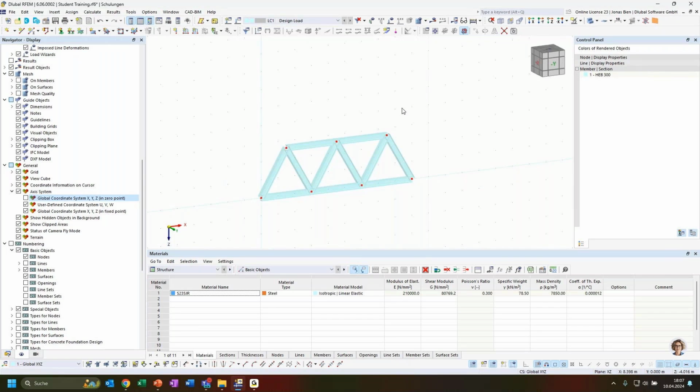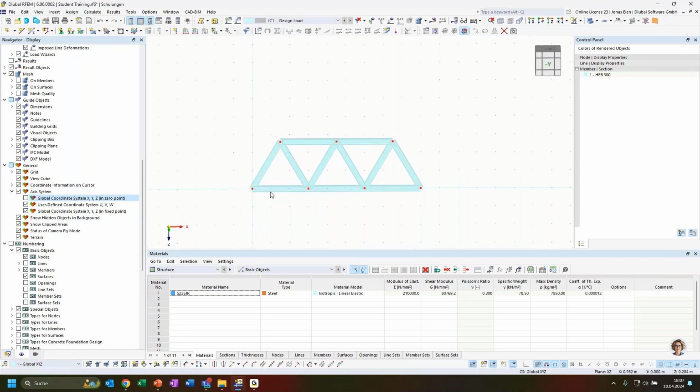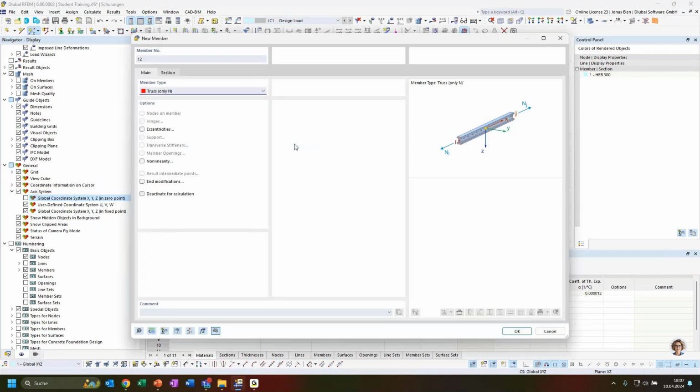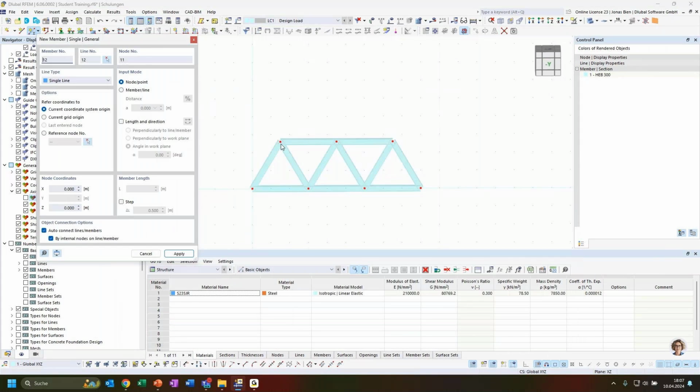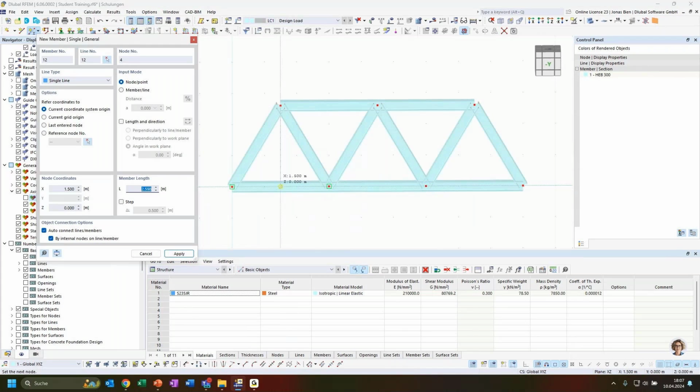So that just leaves me with the missing vertical truss members that, so to say, divide my triangles by half. So I generate additional truss members, and I create them by selecting this upper node of my first triangle, and then I can snap to the midpoint of the first member of the lower chord.